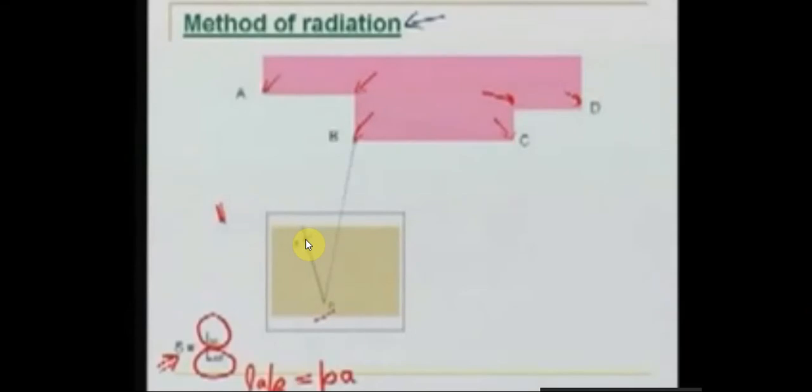Next, similarly, using the alidade, I will sight point B. So this is my sight. After sighting point B, again I will draw a ray against the alidade in this direction on my drawing sheet. Then I will measure the distance between point P and point B on the ground.